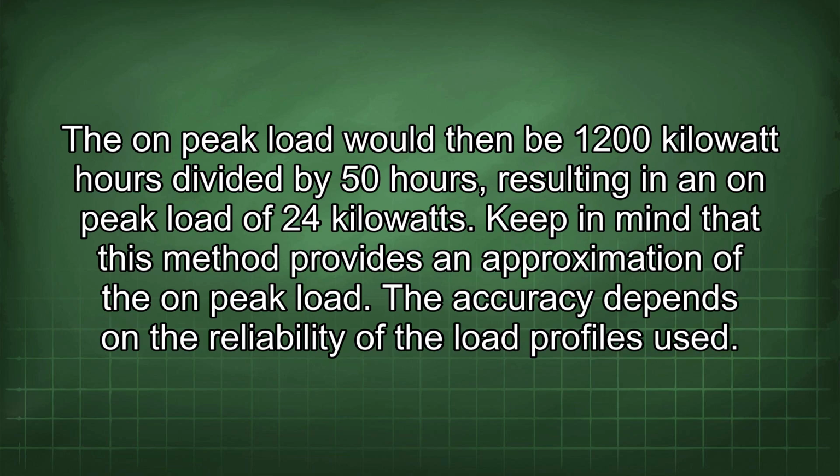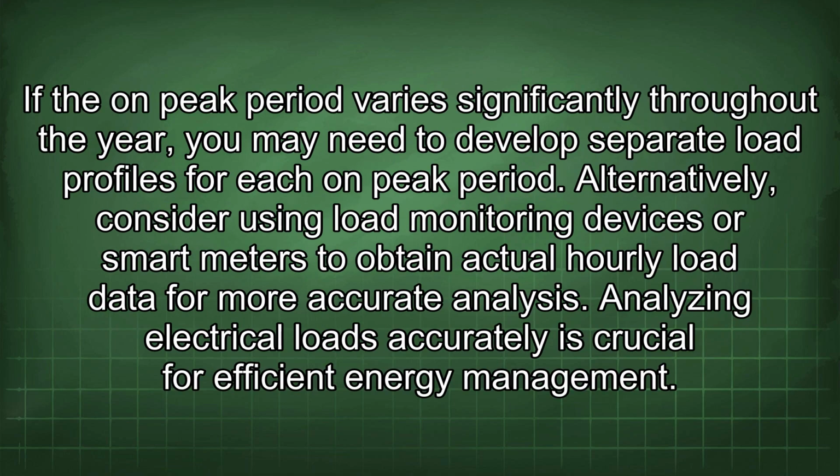kilowatts. Keep in mind that this method provides an approximation of the on-peak load. The accuracy depends on the reliability of the load profiles used. If the on-peak period varies significantly throughout the year, you may need to develop separate load profiles for each on-peak period. Alternatively, consider using load monitoring devices or smart meters to obtain actual hourly load data for more accurate analysis.